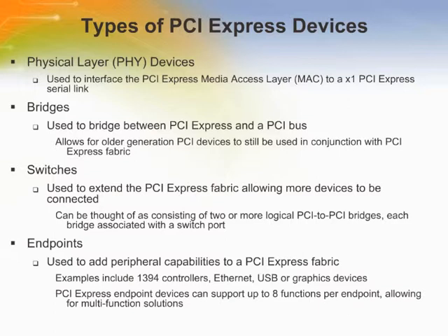PCI Express switch devices are used to extend the PCI Express fabric, allowing for more devices or endpoints to be connected. Endpoints are necessary to add peripheral capabilities to a PCI Express fabric. There are many examples of peripherals, including 1394 controllers, Ethernet, USB, and graphics devices that can take advantage of the high bandwidth capabilities of PCI Express.